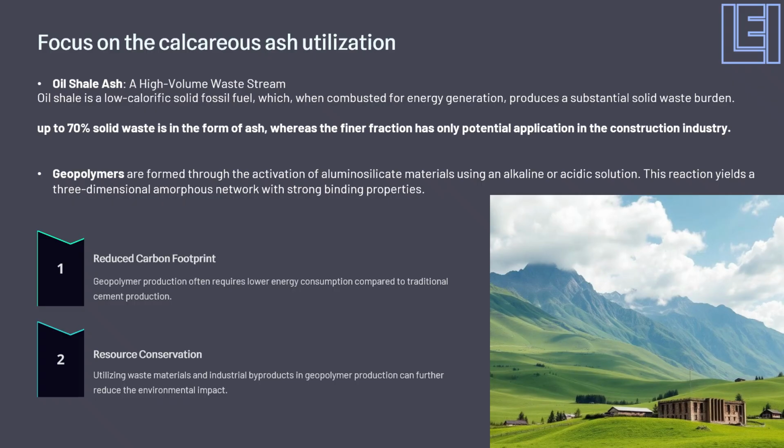Ash derived from the Lithuanian power plant is rich in calcium-bearing phases. Therefore, geopolymerization in alkaline medium requires an additional source of silicate. Therefore, this study focuses on evaluating oil shale ash as a potential binding material in processing of acid-based